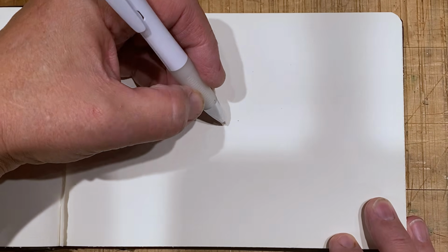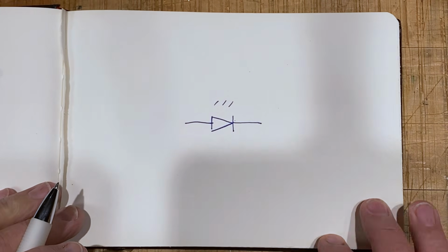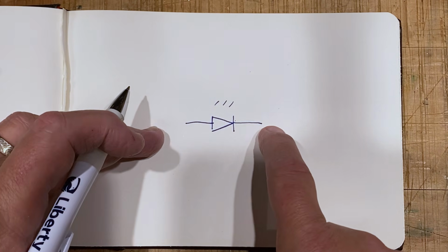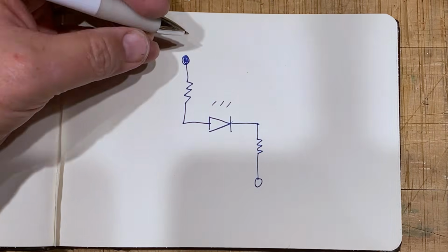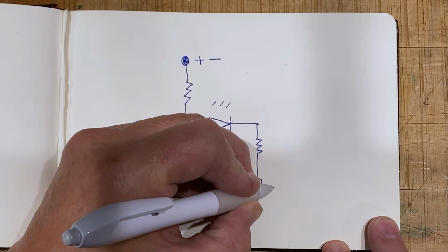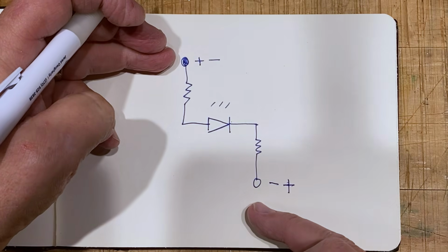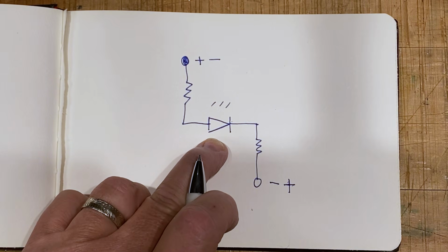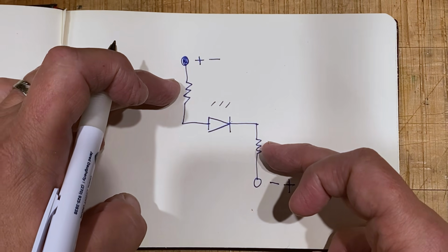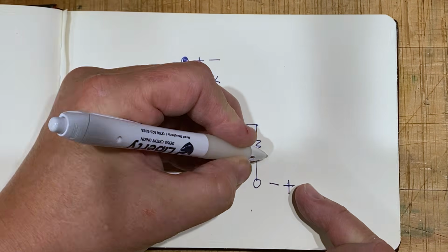Now, beyond the audio switching, I'm also going to want to have some kind of LED indication if the circuit is active or inactive. I set up something like this, where I have positive and negative, negative and positive rails here alternating back and forth. If this is positive and this is forward biased, my LED will illuminate. Now, I won't use 100K resistors here. I will probably use something much lower, up to as high as 10K.